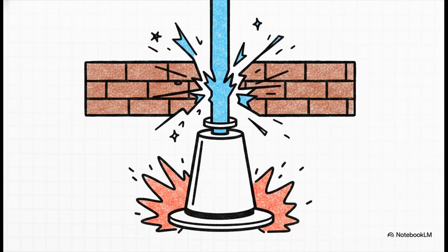First, we need to grasp the macro-level problem we're facing with today's massive global data demands. Our modern networks rely heavily on cost-effective, directly modulated semiconductor lasers, specifically VCSELs, or vertical cavity surface emitting lasers. Direct modulation just means we encode information by rapidly changing the electrical current pumped into the laser. But here's the kicker. Researchers have found that standard VCSELs hit a stubborn physical ceiling right around 30 gigahertz. This 30 gigahertz wall exists mainly because of hard limits on how much heat, electrical resistance, and energy these materials can handle before the signal degrades completely.